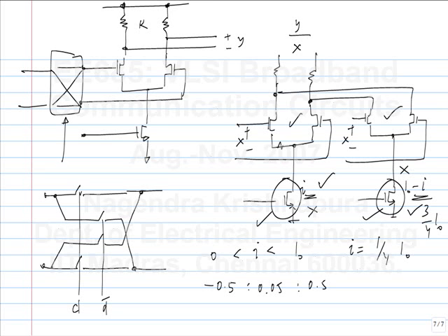You degenerate with resistors. That's an idea to make it linear. What happens now? So now the GM won't vary. Yeah, okay. So there are other ways of doing it. Let's not go into that now. So the idea was, you do a degeneration, and that's a completely different way of varying the GM. While his point is, now if you reduce the current, the linearity of this differential pair reduces.